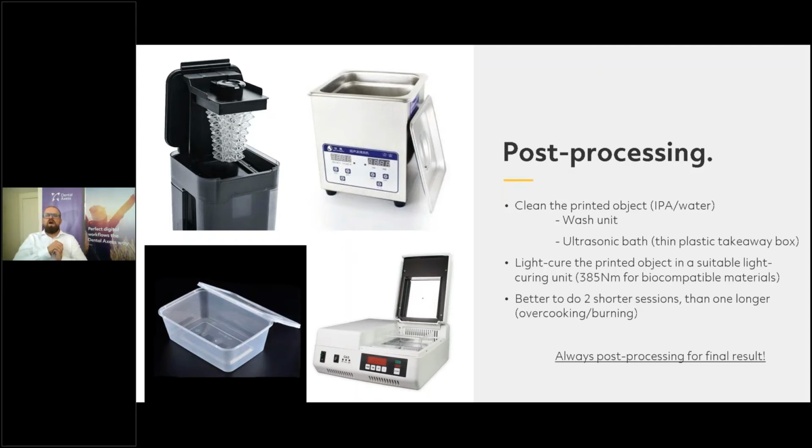And if you now expose it for the full 5-6 minutes or whatever it takes for your material, directly to full UV light, you can understand that it generates a lot of heat and you can have overcooking and burning. So that's one of my tips: do shorter sessions, let it rest, do another session. But always you need post-processing for a final result.